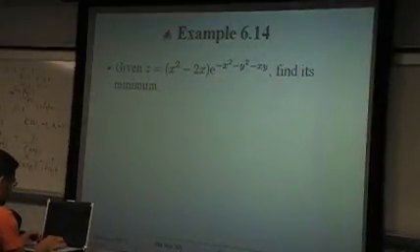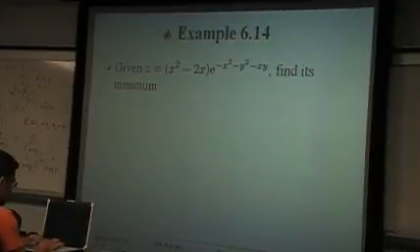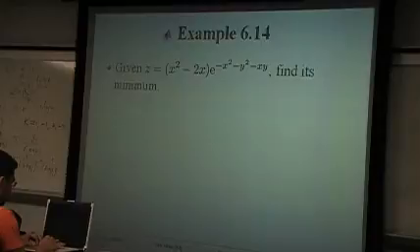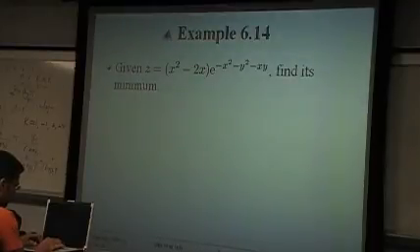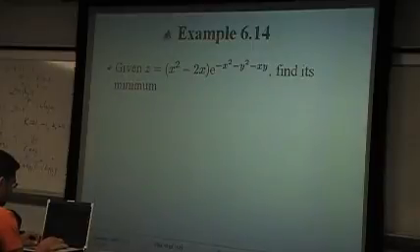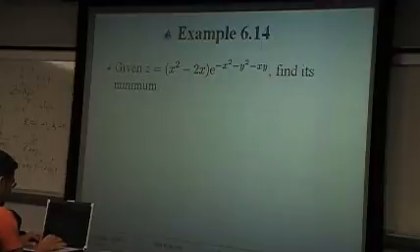To solve this problem, again, like the equation solver, we have to specify variables to compose an x vector. For this example, we assign x1 equal to x, and x2 equal to y, and again, x should be a vector. This is the first thing we have to do.